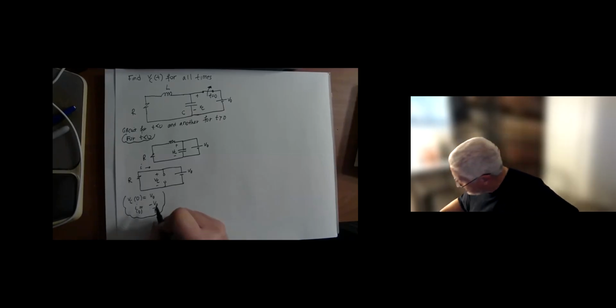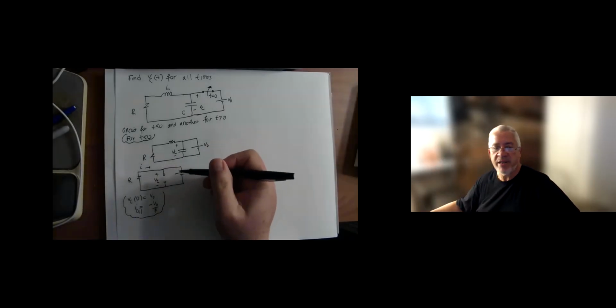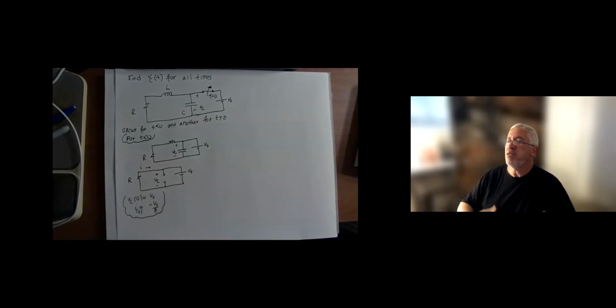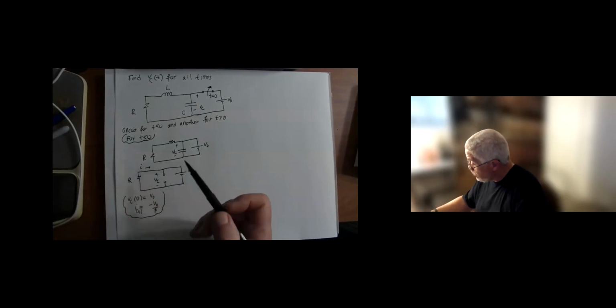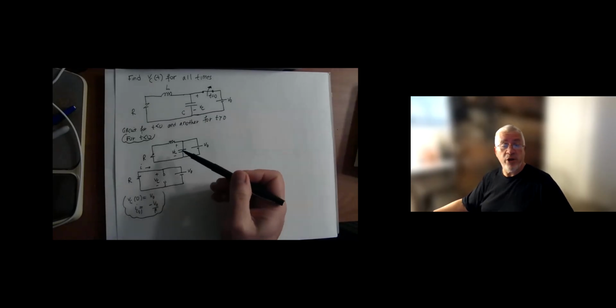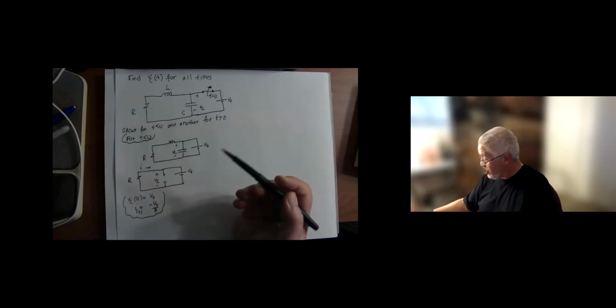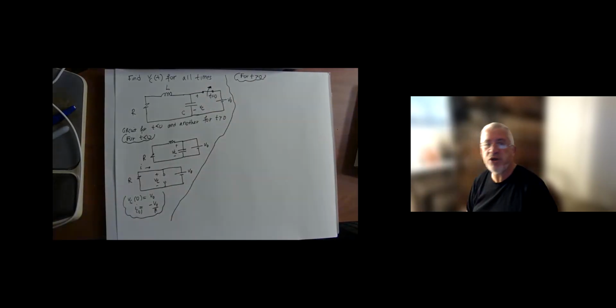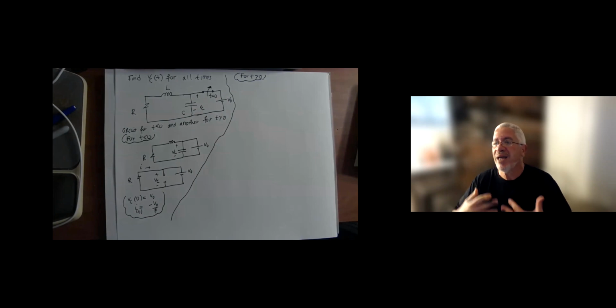Okay, so typically this is what we said, the first time period is a simple circuit. So when I talk about using mesh and nodal, I'm mostly talking about once the switch has moved, because the inductor and the capacitor are now going to wake up at t equals 0 because there's been a change in the circuit that forced them to behave like inductors and capacitors. For t less than 0, what you're doing essentially is charging the inductor and the capacitor with a DC source. So now we're going to talk about what happened. So let's do separation here. Let's look at t greater than 0. The procedures that we talked about, nodal and mesh, relate to that time period.